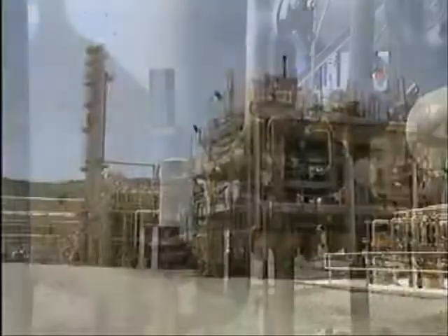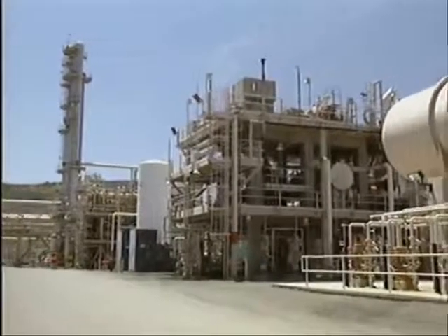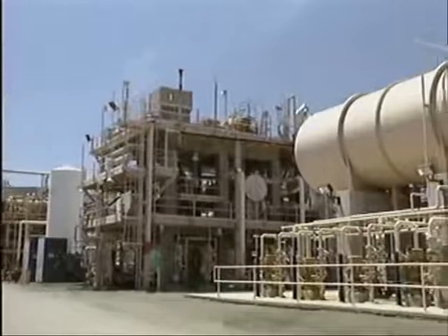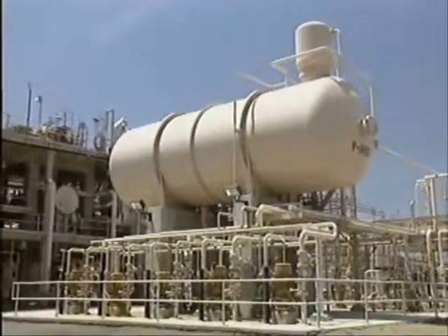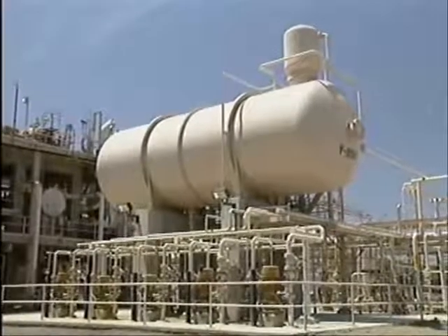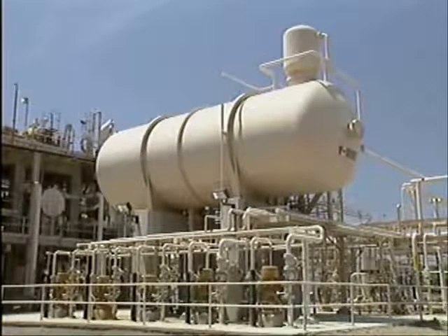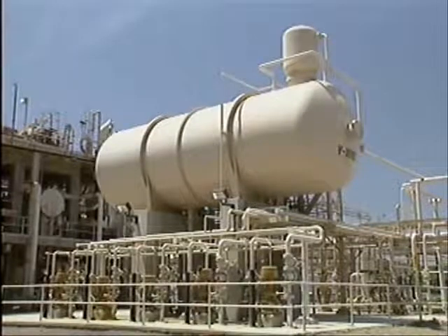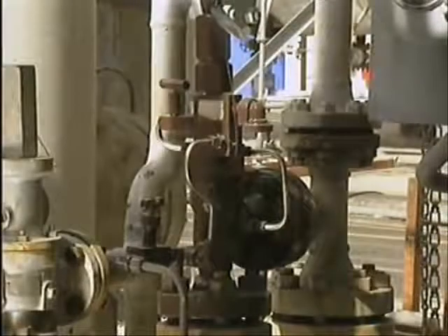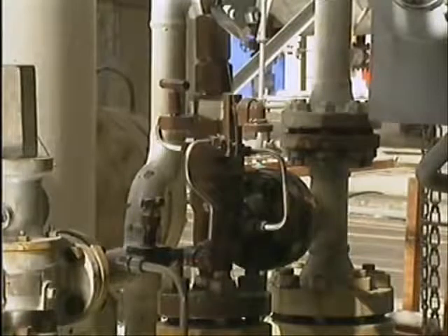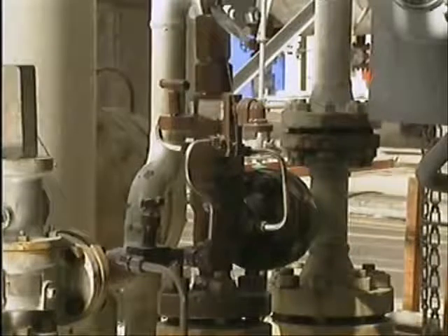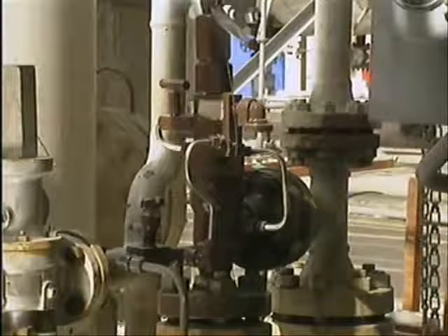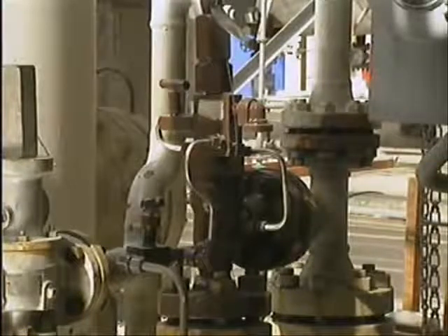valve repairs. You see, by law, safety valves can't be isolated from the systems that they protect because of the damage that could occur if the systems were operated without protection. So, whenever a safety valve is damaged, its system must be shut down while repairs are made. Pilot-actuated relief valves, however, can be isolated from a system because they're not a primary part of the system's safeguards. So, the pilot-actuated relief valves can be used and then repaired if necessary without having to shut down the system.